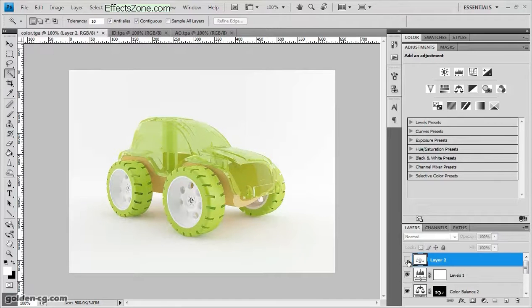So, without ambient occlusion and with ambient occlusion, there are small shadows on the edges and borders of each object, but we cannot achieve it with Max and V-Ray. So we need to use the ambient occlusion layer. Almost all projects will use this ambient occlusion. If it is a movie, it will be mixed with some software such as After Effects or Combustion, or if it is a picture, we can mix it in Photoshop. So it gives depth to our work. You see here, this part and this part without ambient occlusion look so flat, and now look nice and natural.